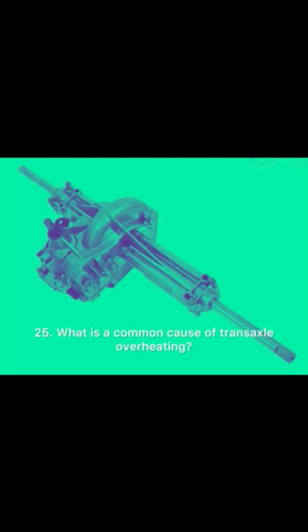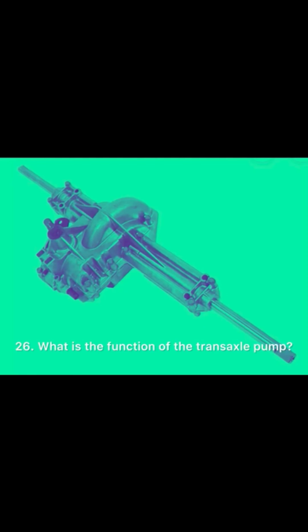25. What is a common cause of transaxle overheating? Low transmission fluid level, poor cooling, or blockages. 26. What is the function of the transaxle pump? To circulate the transmission fluid. 27. What is a transaxle filter? A component that filters the transmission fluid.